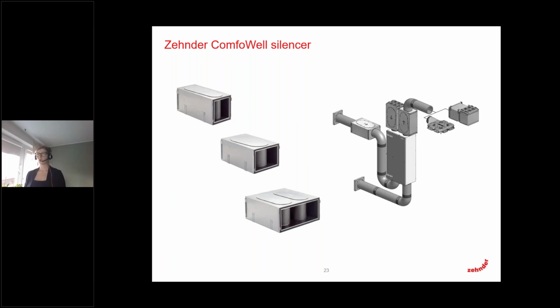Also, what is good to know is that with this silencer you can see the opening panels here, that it's possible to unscrew the screws and take out this silencing material if there is full system cleaning planned. And thanks to this, when the silencer is opened, we can do the tube system cleaning quite nicely, and it's helpful.